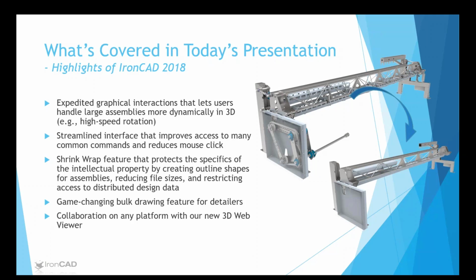We'll next jump over into our bulk creation capabilities, which is one of our key things in 2018, which we believe is a game changer in the industry that actually speeds up the process from taking your 3D data into the 2D drawing environment, basically creating all your views and all your layouts and sheets and drawings for your model, and simply all you have to do is detail that process. So really streamlining the tedious task of creating drawing views and multiple sheets for all your files, your assembly files.